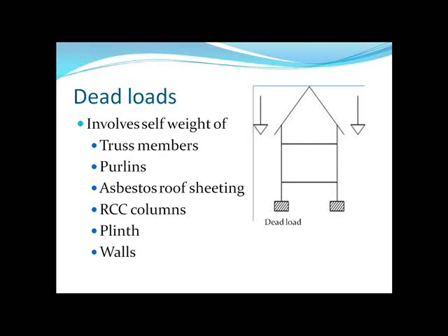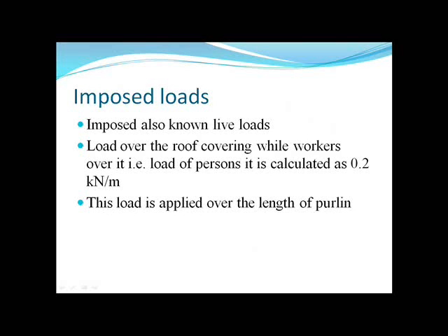Structures carry different types of loads, and the structural element has to be designed for all the loads that are likely to come on the structure in its entire lifespan. Coming to the dead load, it is a permanent load on the structure, and it includes the weight of all elements. Coming to our structure, these elements are truss members, purlins, and the asbestos roof sheetings.